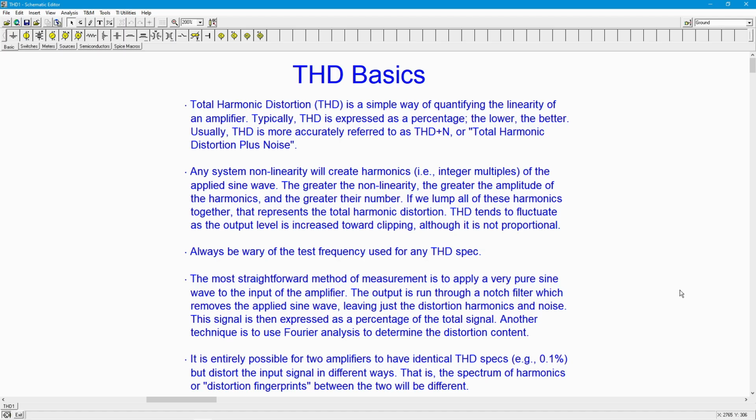And how that happens is also a variable depending on the kind of amplifier you have. You'll discover that for a Class A amplifier, the distortion you get according to level will behave a little bit differently than it does for a Class B amplifier. I'll talk about this momentarily, but there are a lot of variables you have to consider here.